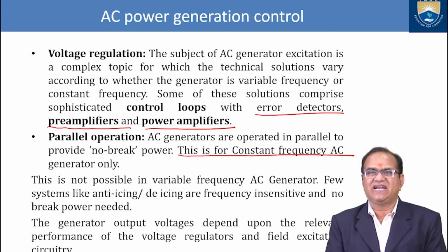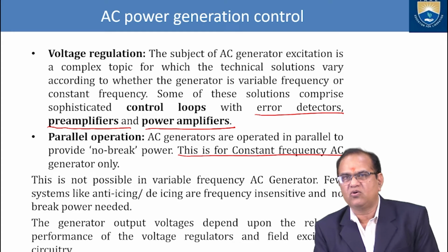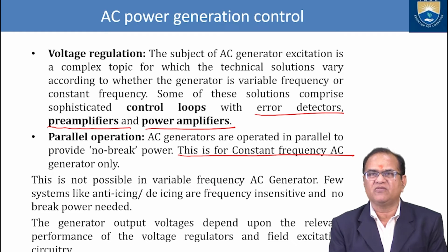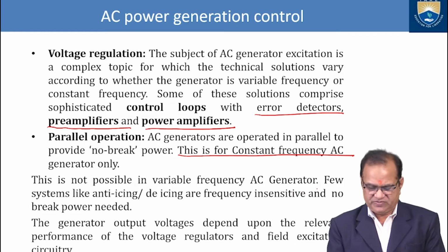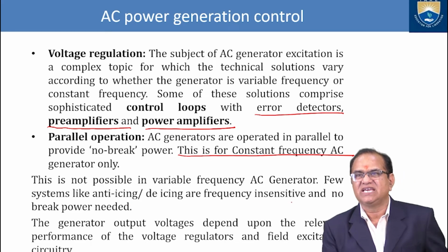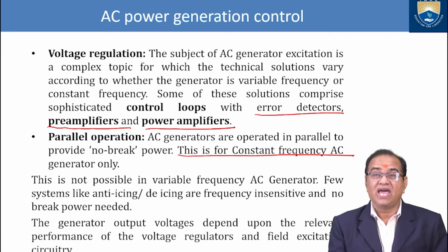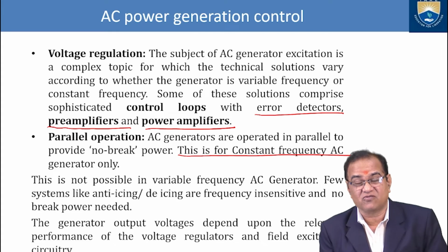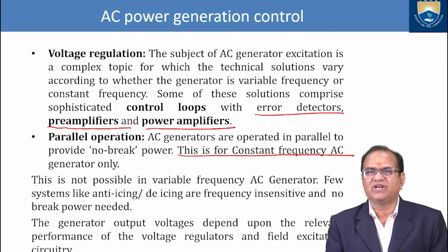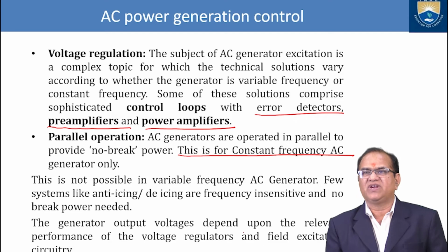Few systems like anti-icing and de-icing are frequency insensitive and no break power is needed. So for anti-icing and de-icing, break power is not required. It should be very smooth, and it should always function. The generator output voltage depends upon the relevant performance of the voltage regulator and field excitation.